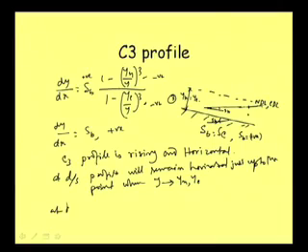Well, then at downstream, similarly we see that y is approaching 0, but again the depth cannot start from a 0 depth as we know. So, physically depth will not be equal to 0, but if it becomes 0 somehow, then it becomes infinity here. So, infinity by infinity is again undefined. So, dy dx equal to infinity by infinity, that is undefined again.